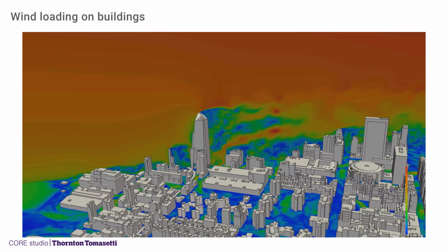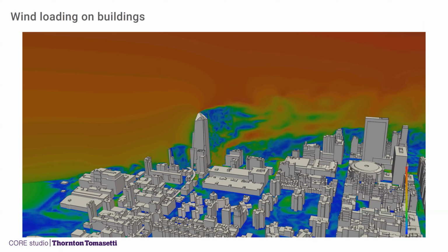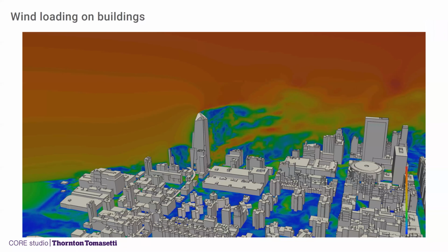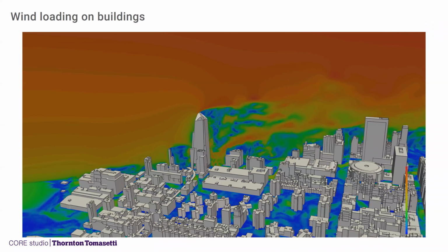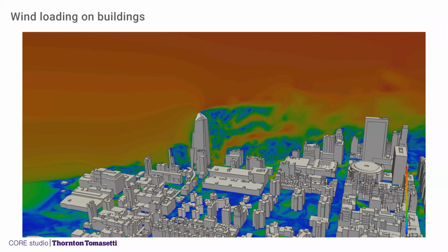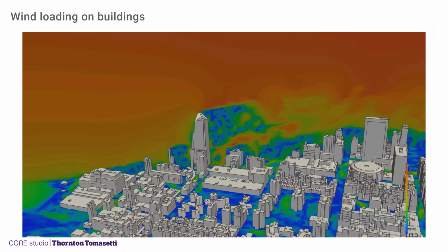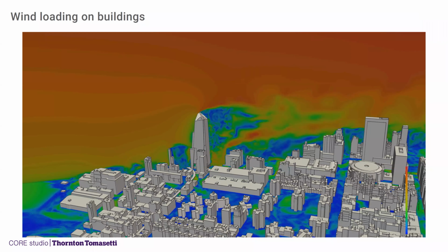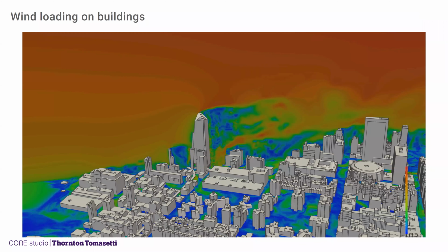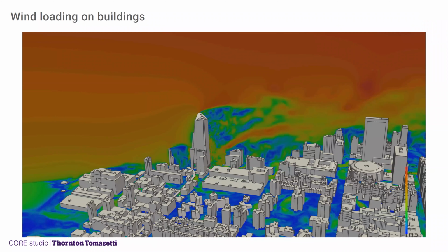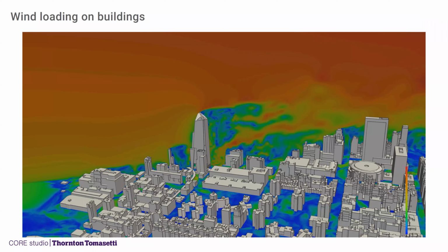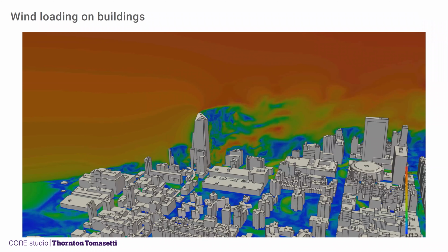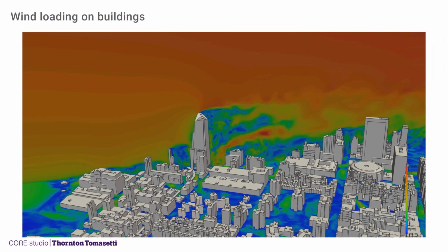To actually apply the CFD, the digital simulations, for early stage wind loading and facade pressures, and how do we go about it? Because it's one thing for pedestrian comfort, which really looks at mean wind speeds and much longer probability patterns, whereas wind loading looks much more at peak intensities and sudden gusts. And that's where it becomes a lot more tricky to do in digital studies, in CFD studies.